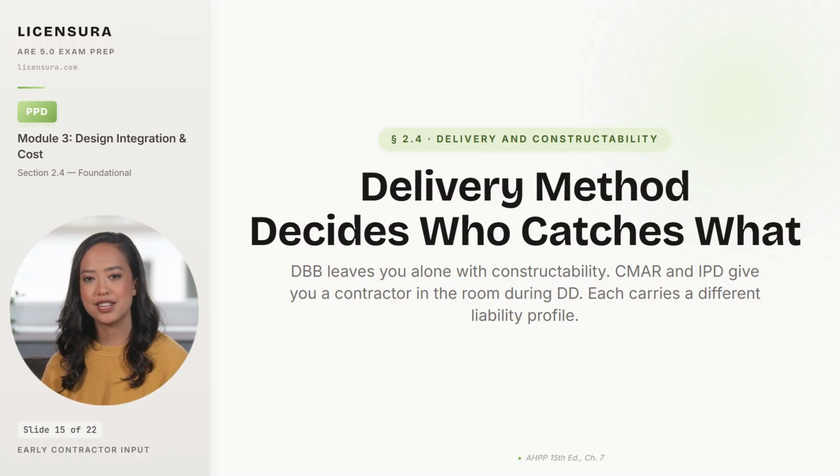And the historical record on DBB shows higher change order rates and more lawsuits because no one with a hammer reviewed the drawings before they were bid. In CMAR, the construction manager joins during schematic or design development as an advisor, bringing constructability and cost feedback while the design can still respond. In design build, the designer and builder share a single team from day one. In IPD, every party shares risk and reward from programming onward. The exam will fail you on a question where the right answer hinges on which delivery method is in play if you quote DBB constructability advice for an IPD project.